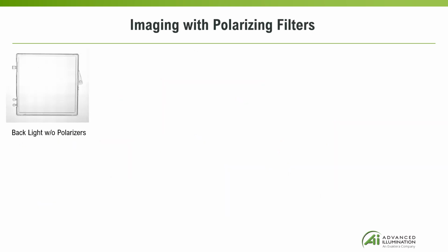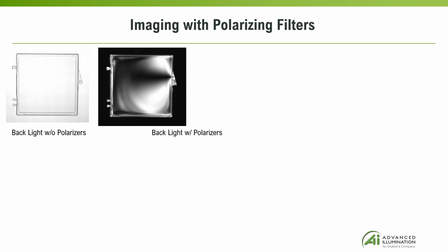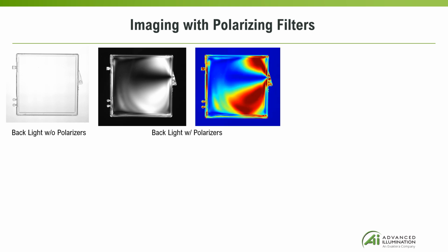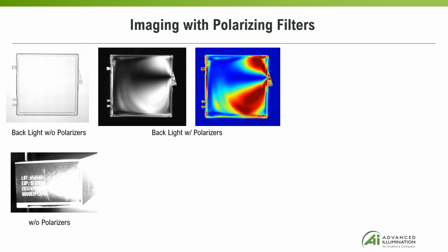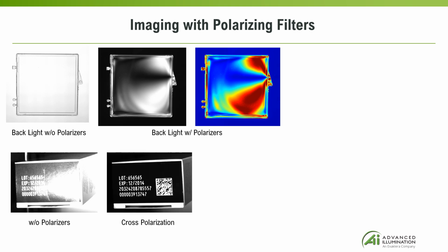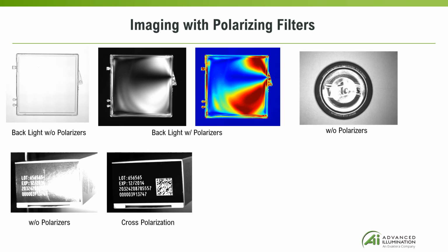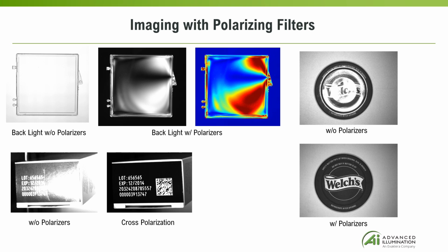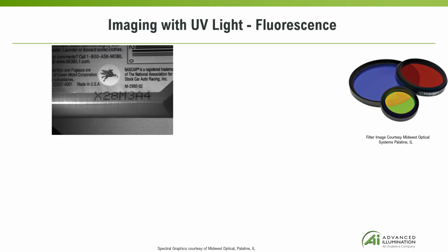Polarized backlighting is best used to detect internal stressing or structural damage in transparent materials. Polarization in machine vision is also employed to primarily block specular glare reflections from surfaces that would otherwise preclude a successful feature identification and inspection. Since the light intensity will be reduced by 50% or more, you will have to increase your f-stop, which may reduce your line speeds and feeds.